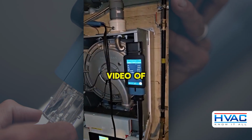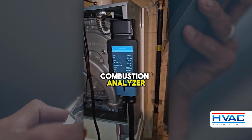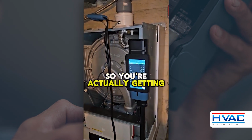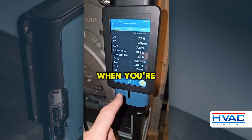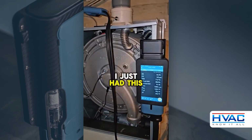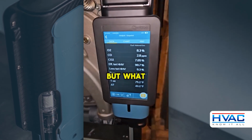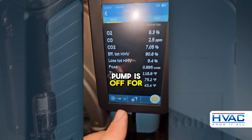So I did a van video showing how you manually set your combustion analyzer, specifically the Seitron NOVO, to manual mode, so you're actually getting the intake air temperature rather than the room air temperature when you're talking about T air. I just had this thing running and the numbers are just kind of all over the place because I just shut it off. But what I want to do is show you how to do this. So right now my pump is off for the analyzer.